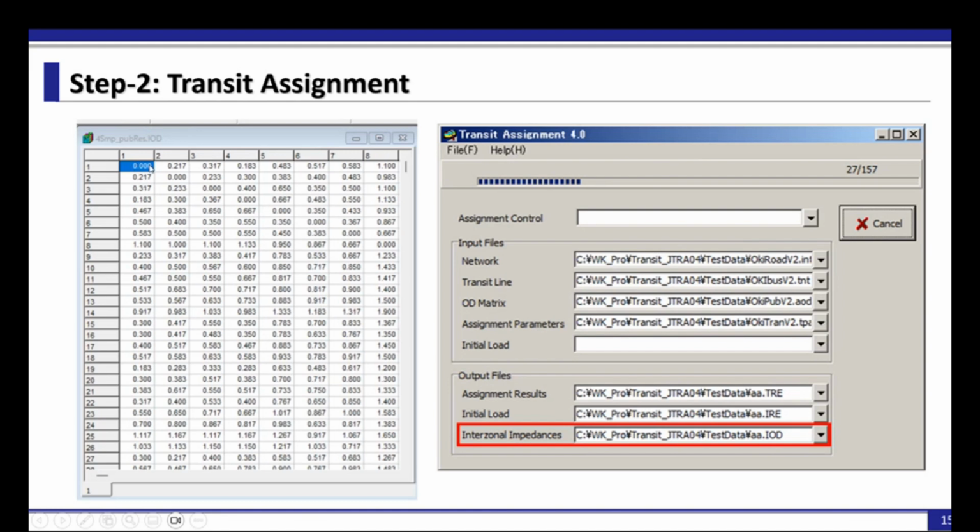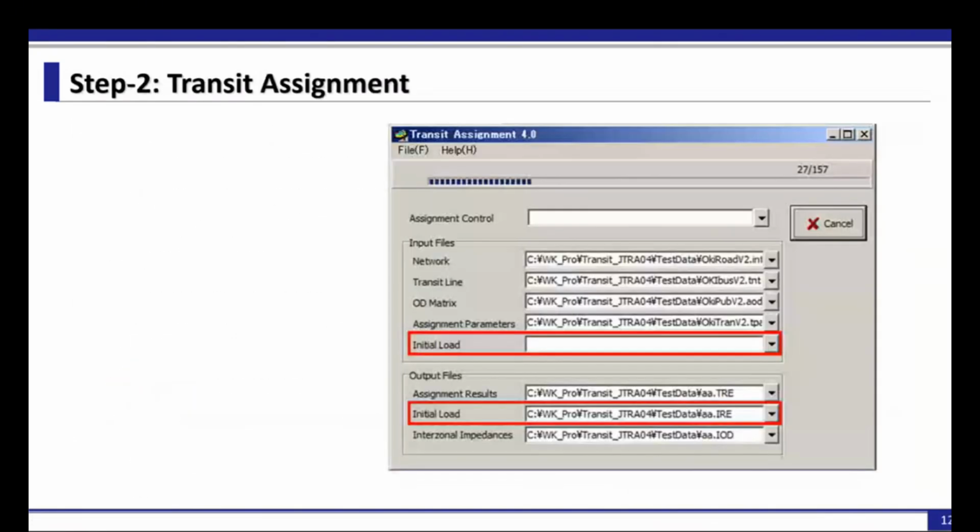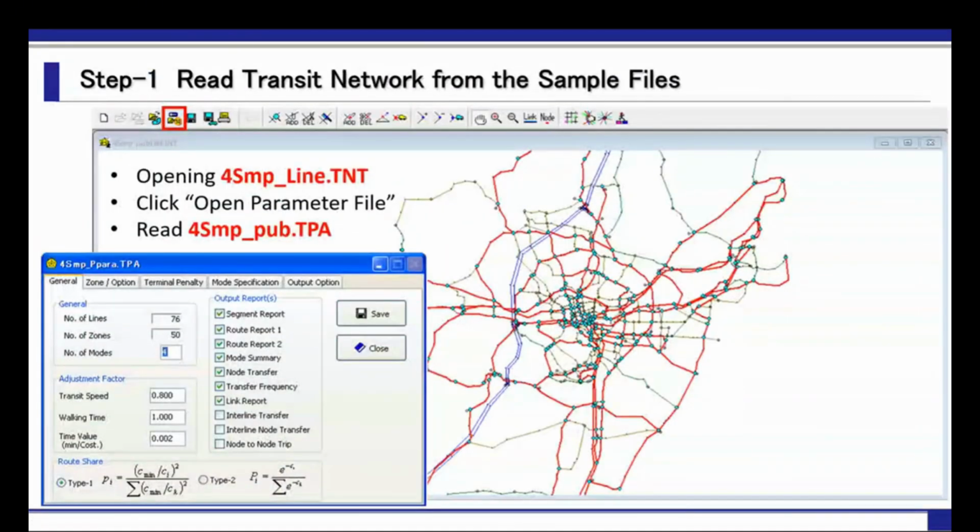So from zone 1 to zone 2, 3, 4, 5 to 17, the generalized cost by the travel OD pair can be generated. From this result, for example, for some routes in some OD pairs, for example from zone A to zone B, so many transfers are required.